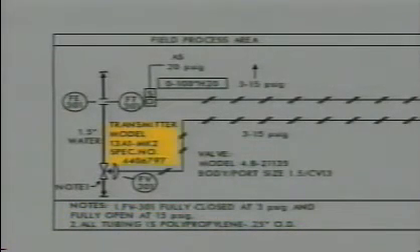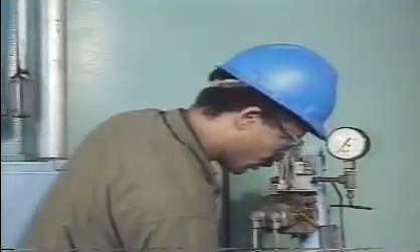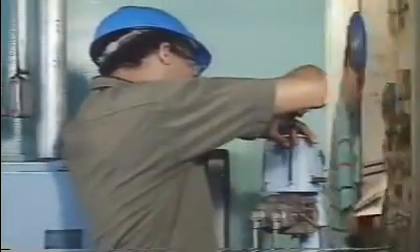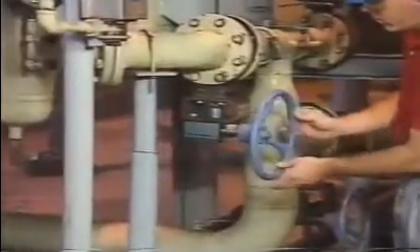The body of the diagram might also include equipment specifications, usually a model number, size, and other details about a specific instrument is included. In some cases, you might find this information listed in a separate section. Equipment specifications are optional, and whether or not they are included will depend on your facility. Having this information, though, is especially useful when parts need to be replaced. Each of the symbols and references we've discussed gives you additional information about the loop and the instruments. You can look in your workbook to find more about symbols and references.